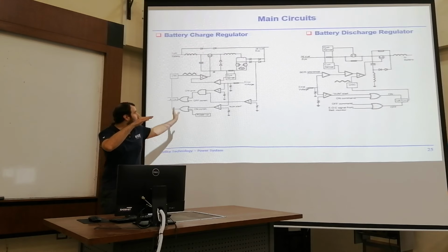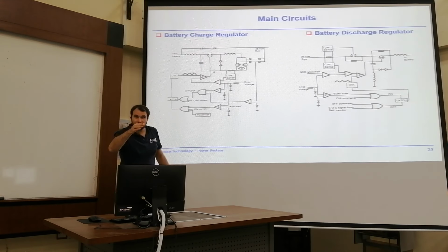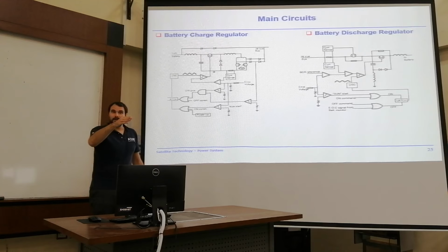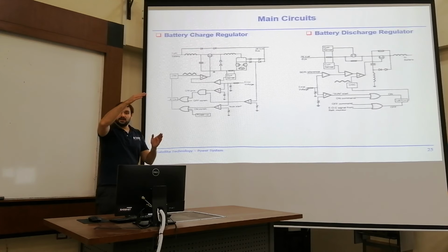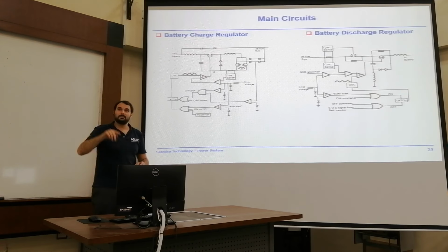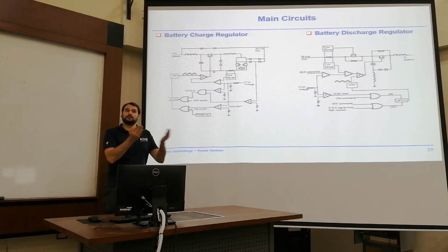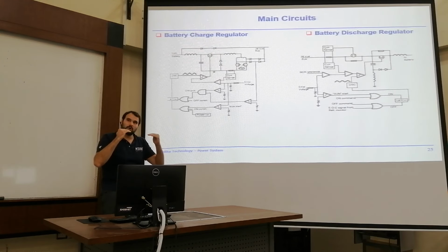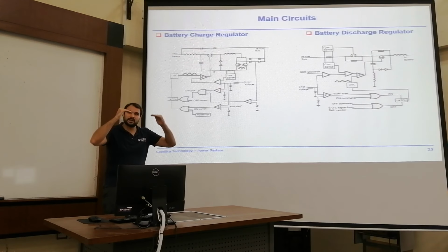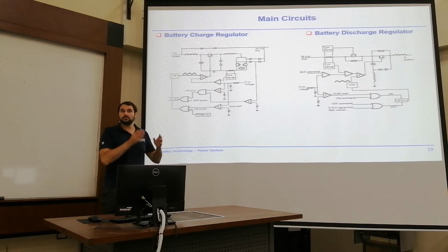So all the output is now being fed by the coil, and it decays. But instead of letting it decay to zero, you switch it back on and recharge. By dynamically switching on and off, you basically can decide where you want to land with your voltage level, simply by the duty cycle of on and off.